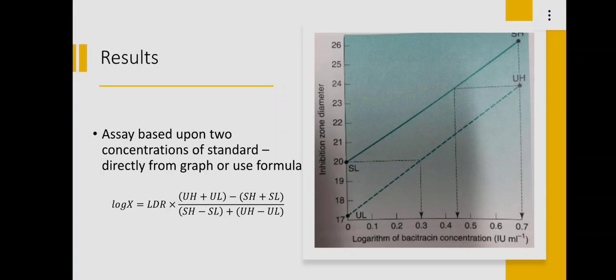During measurement, the measurement can be taken directly using calipers, but the most precise and accurate method would be to project those shapes on a screen and take measurements from there. So that's kind of a magnification activity, which would make measurement much easier and more accurate.